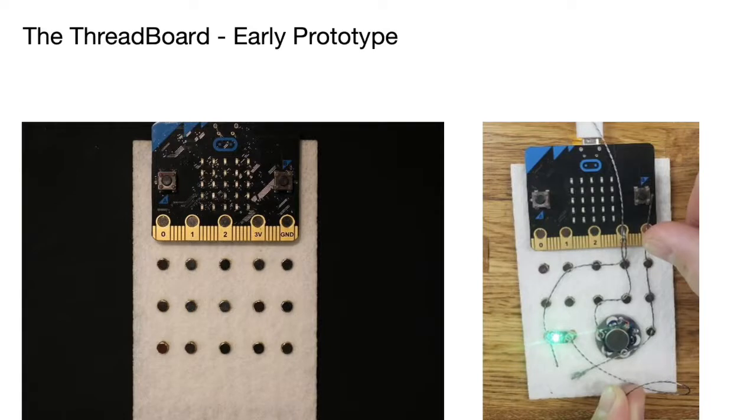This is an early prototype of the ThreadBoard that served as a proof of concept that we can embed magnets into pre-existing microcontrollers easily, and that they would allow for an intuitive connection with the magnets embedded into stiff felt. The main issue with this design was the layout restrictions. The ThreadBoard could only support one or two actuators or sensors, and also due to the layout design, the user could not easily utilize all the adjacent pins available on the micro:bit.